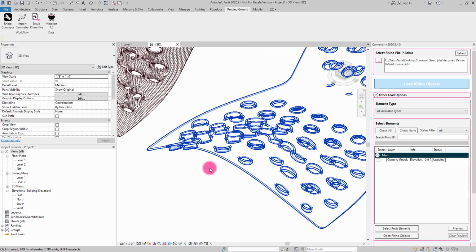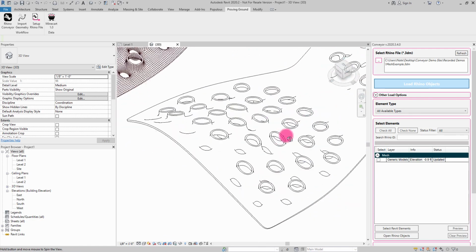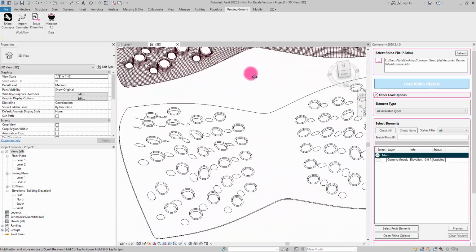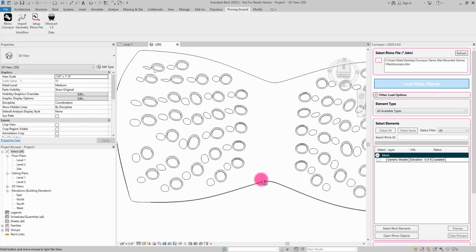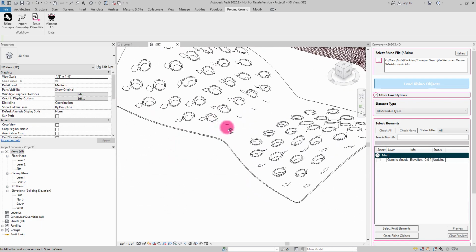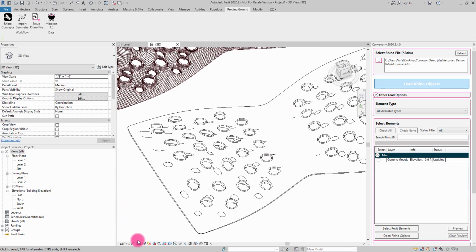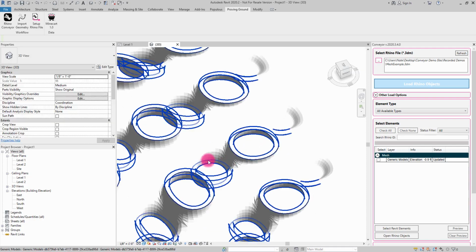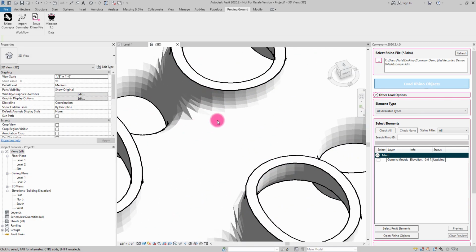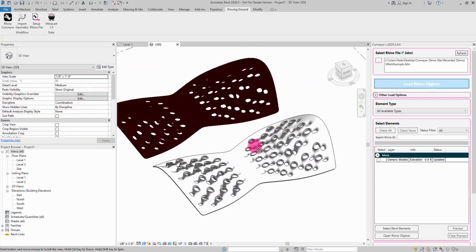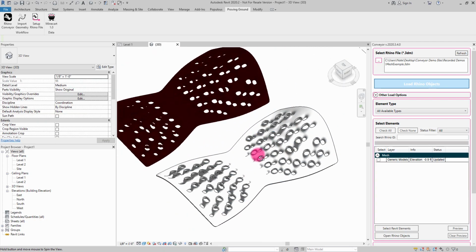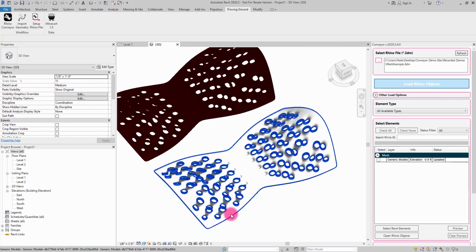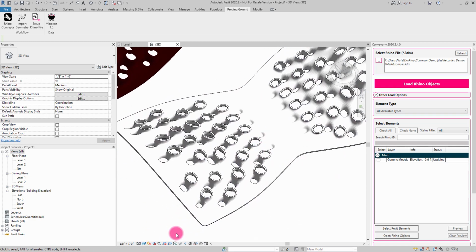The edges of the mesh where you have creases are going to be visible, but all the intermediary polygons that you see in this DWG import are gone, which makes this very useful as a kind of documentation background. If I go to shaded mode, we can see the polygons are still there. This is a mesh that has not changed, but the edges themselves are no longer visible. What we've also found to be pretty novel about this workflow and this particular type of mesh is how well they cut. They're pretty lightweight representations as we've brought them in.